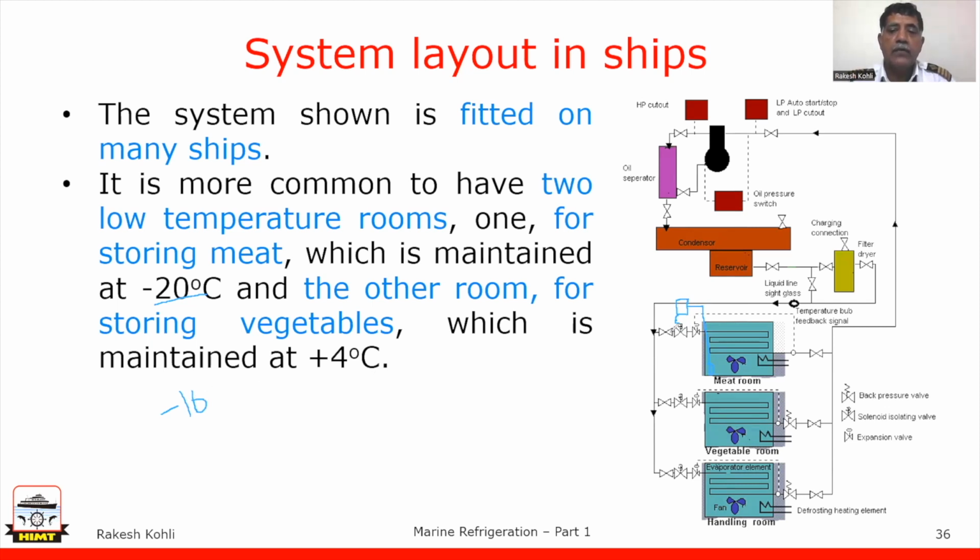It will pull up the valve and allow the liquid to flow through this, and a fan will be running. Fan will send cool air on top of the coils and cool it further. From minus 16 air will be sent, and it will cool down to minus 20 degrees. Once the room temperature comes to minus 20 degrees, this solenoid valve will send a signal to switch off the valve. So then the valve is switched off, and the gas will not flow through this, the liquid.